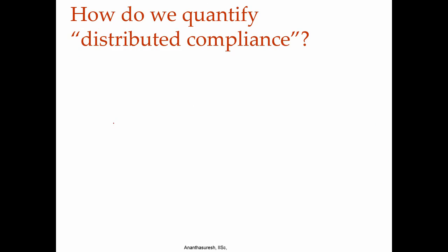dependent on how we quantify this distributed compliance. How do we quantify what is distributed compliance? What do we need to do? We need to get a compliant mechanism. Can you tell that this is a discrete compliant mechanism? Probably it is easy, because we see that there are a few portions where the strain energy is concentrated in a discrete way. That is where most of the elastic deformation takes place. You can call it a discrete compliant mechanism.